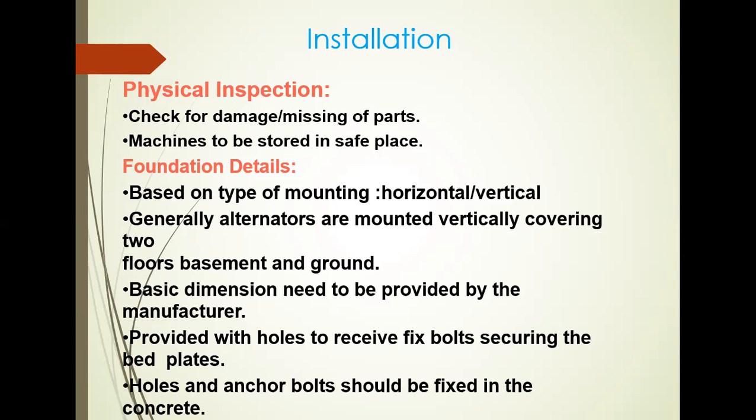That is the specification of the machine, and we can mount or install the machine accordingly. The basic dimensions need to be provided by the manufacturer, with holes to receive fixed bolts securing the bed plates. Holes and anchor bolts should be fixed in the concrete.